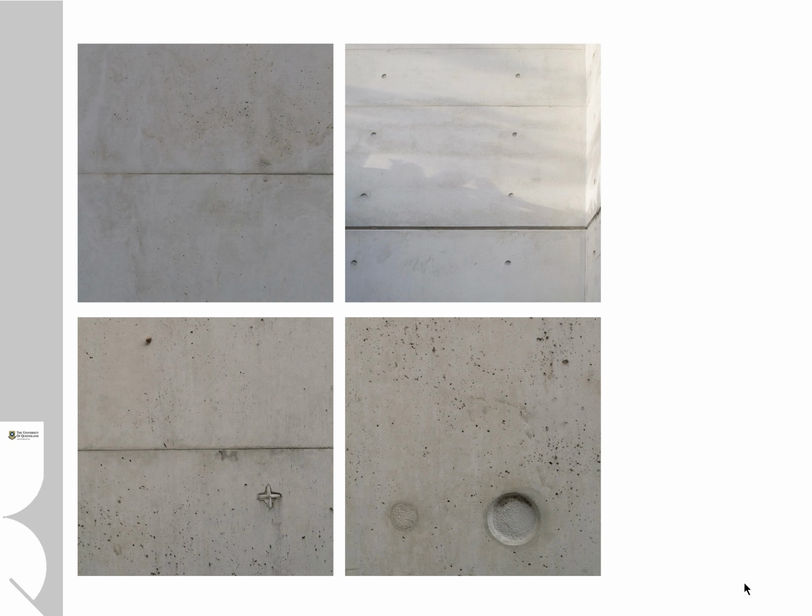These bolts are removed when the formwork is removed, and then the builder goes along and fills them in with grout. So an off-form concrete wall will always have a series of these holes which are evenly spaced to bind the two sides of the formwork together during construction.